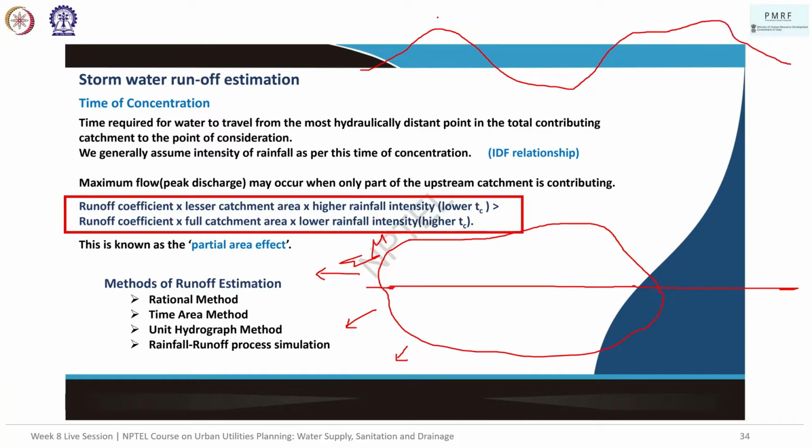From this point to this point, all the water starts flowing to the lowest point. Say you locate the drain somewhere here, ideally. All the water starts flowing like this, right? And anything that falls here will be flowing in the other direction. So this area is called the watershed, right?